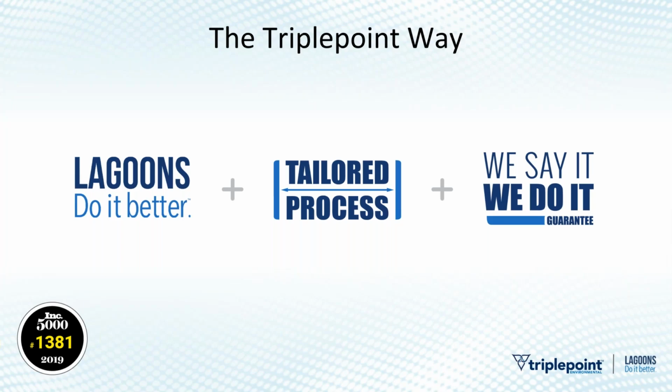So lagoons can do it better to the point where we can modify lagoons to give you an effluent as good or better than the activated sludge plant. But it does require a bit of a tailored approach. There is no one-size-fits-all solution to lagoons. Every lagoon's different. Some are fat, some are deep, some are wide. Some have high flow, some have low flow. Same with loading. So the solution to each individual plant tends to be different from the plant that we did prior to that. So it does require a tailored process.